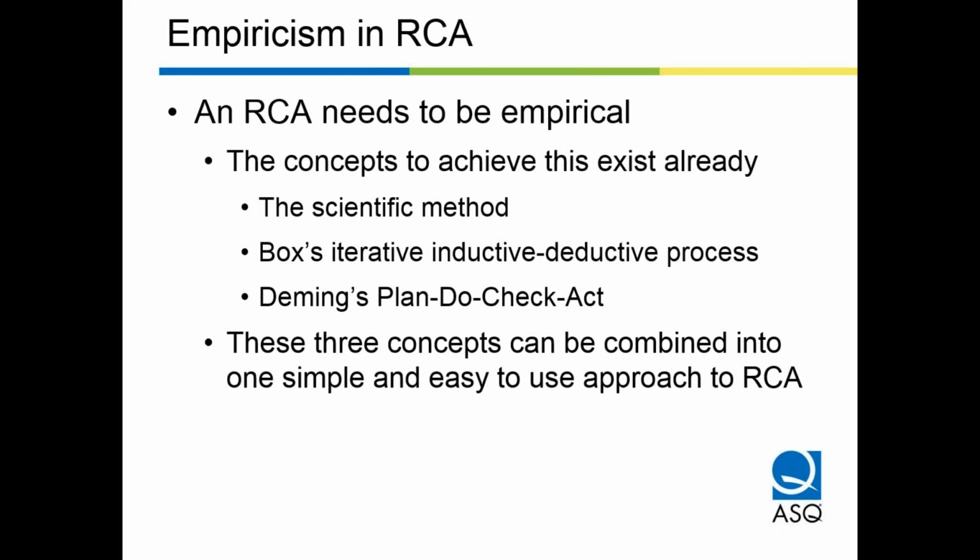Let's think of this. If I told you the part is failing, well, we know something. We know it failed. It did not work, but that's not really much to work with. But what if I said 17 out of 20? Now we've got more information. Let's take it to the next step, and I said the 10 millimeter dimension plus or minus 2 millimeters is measuring 14 on 17 out of 20 parts. We have numbers behind it. We have far more knowledge.